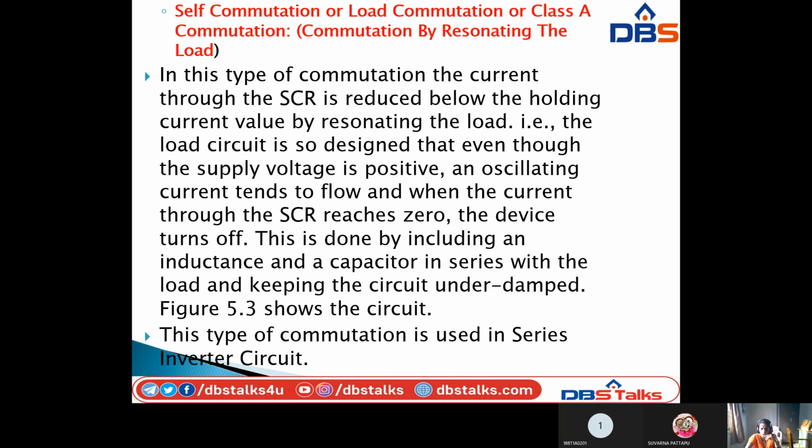Self commutation, or load commutation, or class A commutation, is commutation by resonating the load. In this type of commutation, the current through the SCR is reduced below the holding current value by resonating the load.